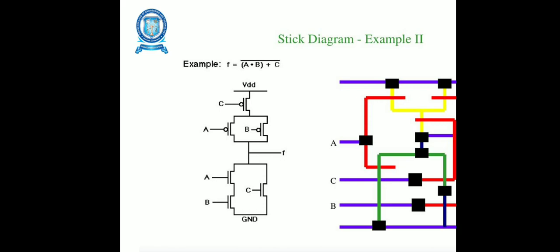This process needs design rules that should be a controllable, reproducible process. Here we use lambda based design rules, which are based on the single parameter lambda. If these design rules are obeyed, then the mask will be produced and work on the circuits. All the paths in all the layers are specified in lambda units, and this is also used to preserve the topological features on the chip.